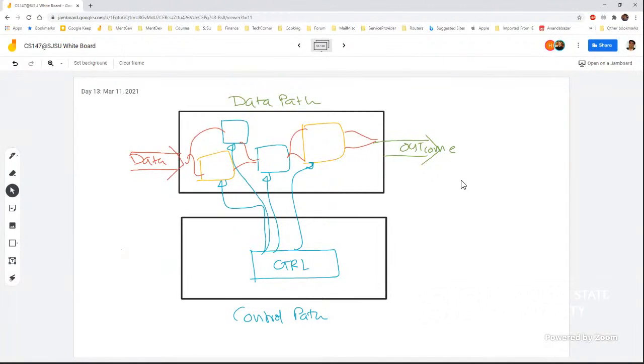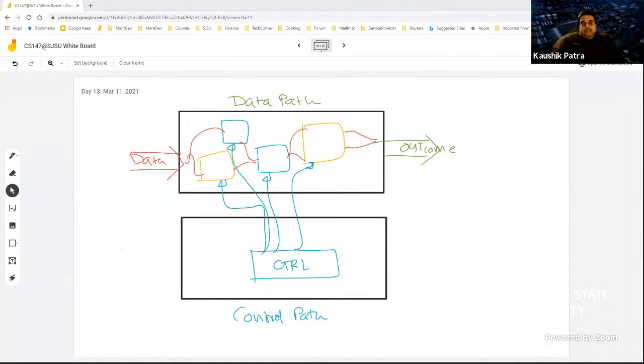With respect to that, we just started to design our own processor at the component level, at the gate level. What we have seen so far is how the instruction fetch data path works. It involves the program counter and one adder, and it gives the address of the next instruction to be fetched from the instruction memory. Then we moved on to the R-type instruction data path, where we introduced the register file and the ALU. It doesn't have any memory component in it. It's basically a register bound operation.